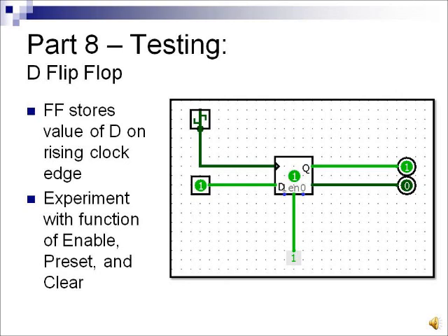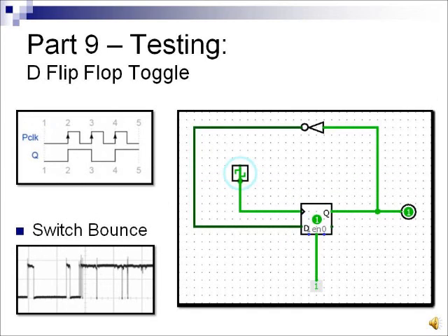Likewise, the clear will set the output to 0 in the same manner when it is asserted high. If both are asserted high, the clear has precedence over the preset. This can introduce noise in the signal, which may lead to unexpected behavior in the circuit. This is shown in the bottom left diagram.